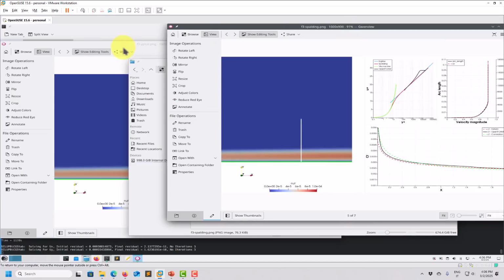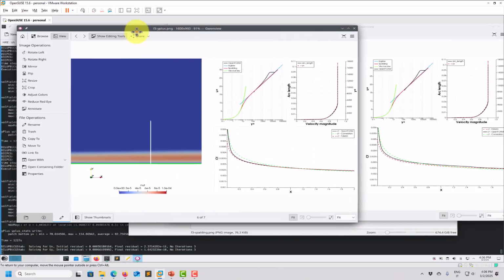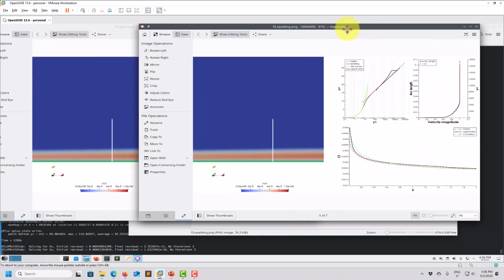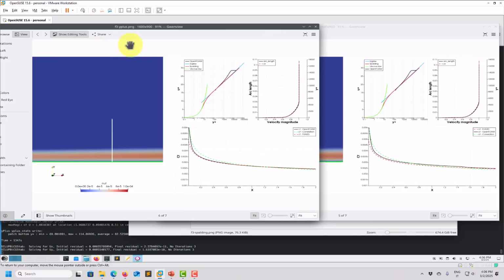Okay, so we have this Spalart here, and if we compare, it looks very similar, but there is a small difference here. Look at what is happening. It's getting the behavior, but then here it has this behavior that seems to be strange. This doesn't mean that the solution is wrong. Actually the trend is correct, but there is something here. This doesn't mean that it's a wrong implementation or that it's divergent. It might be the case that you need to iterate a little bit more.